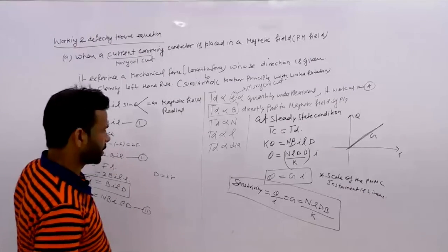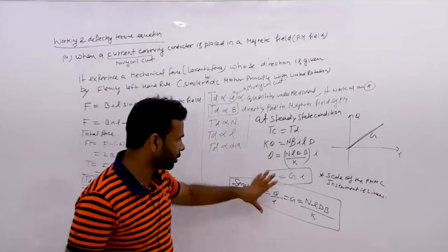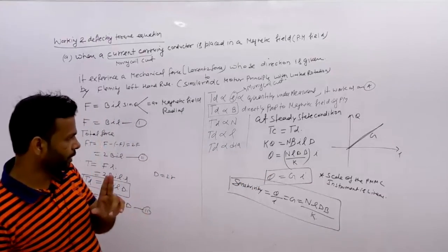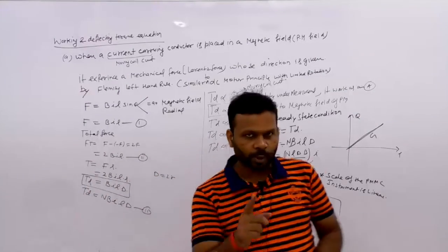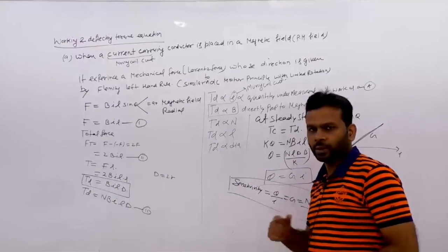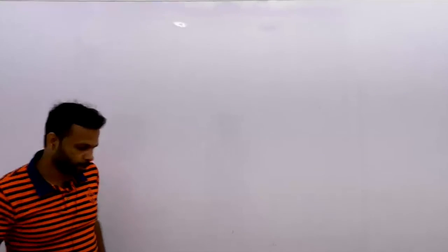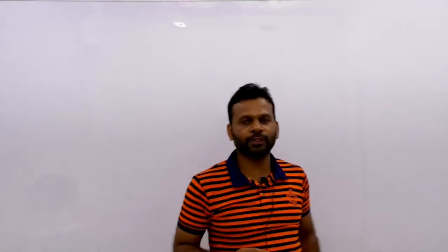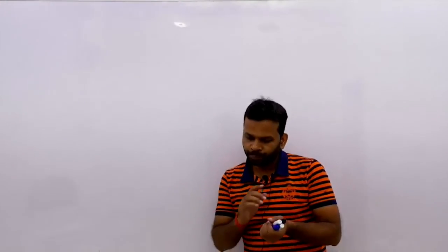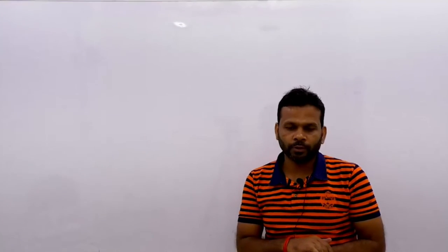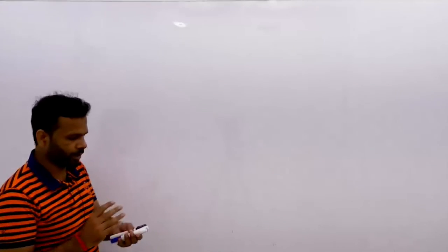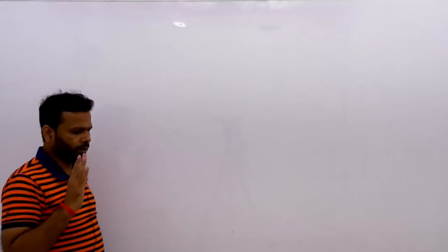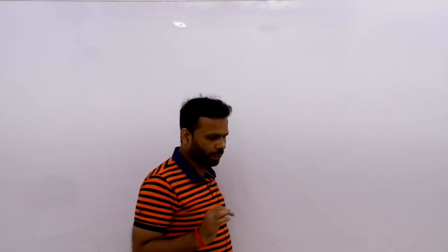So we have covered the deflecting torque and the controlling torque. The last torque in case of a deflecting instrument is damping torque. So now let's see how the damping torque works in the PMMC instrument. Up to here we have seen the deflecting as well as the controlling torque for the PMMC instrument. Now, in the case of your PMMC instrument, damping is provided by the eddy current.